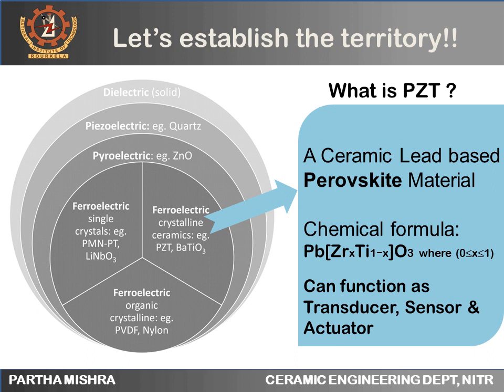So what is PZT? It is a polycrystalline ceramic perovskite material that shows a marked piezoelectric effect. It's a compound consisting of lead, zirconium and titanium, hence the short form PZT, and has the following chemical formula as we can see. It is a lead-based perovskite. We will see this perovskite structure in the next slide when we zoom in to see the unit cell of PZT. PZT is also a dielectric.